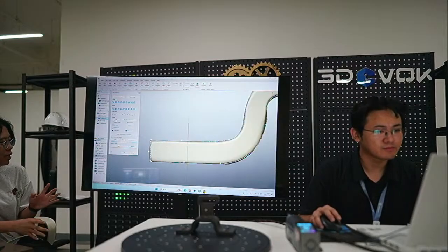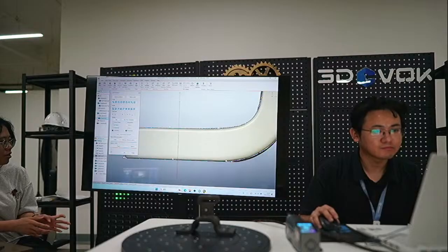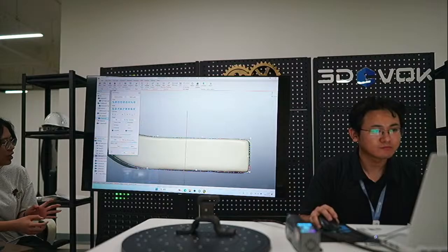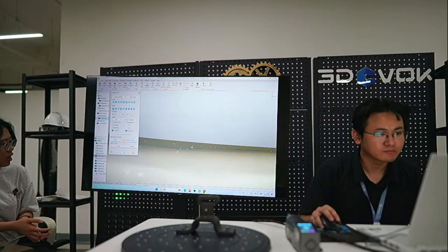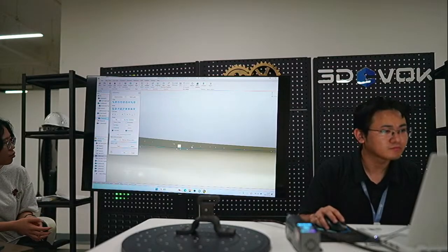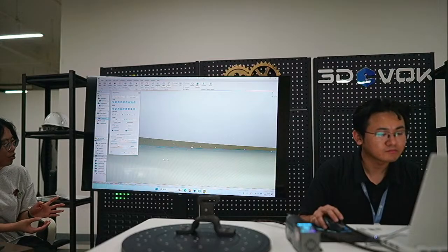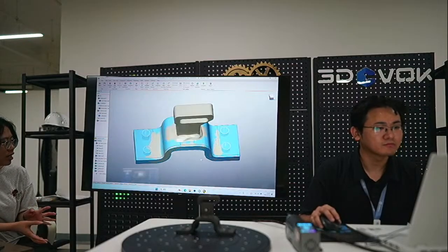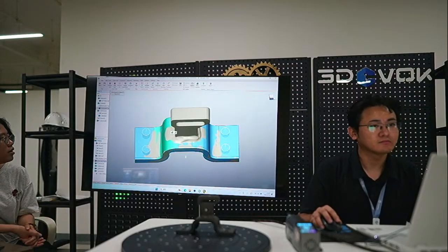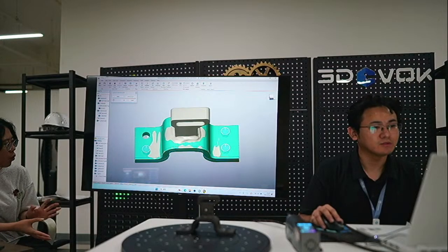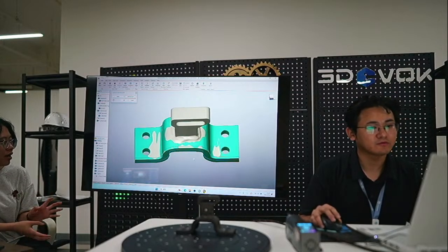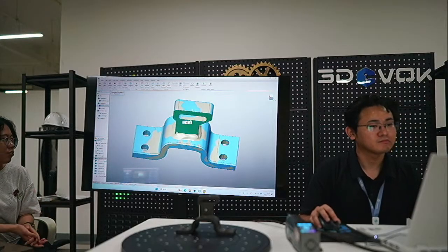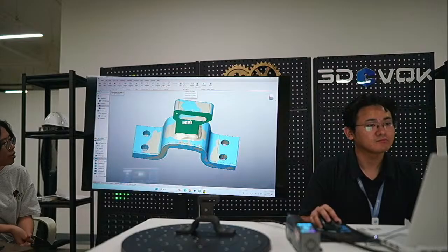Why can we not cut those cylinders? Because we observed that we didn't create a closed curve just now. So we must check every point to remove the unnecessary part and make sure all the lines and the points are joined together. We require the solid so that we can cut the 4 cylinders. So you can see here we have created the 4 holes.